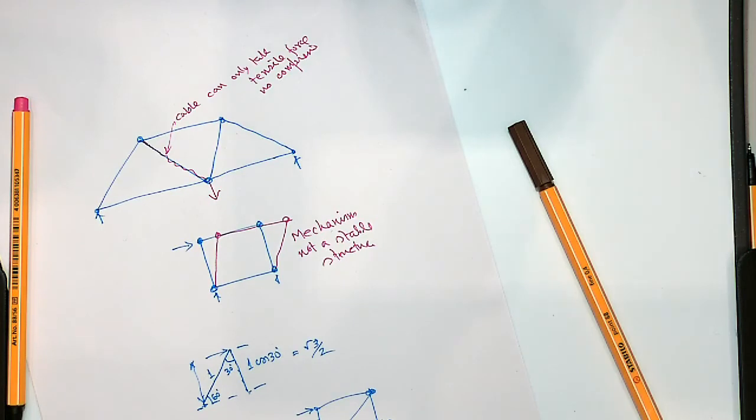Yeah, I just had a question about this question. When I was doing it, because they wanted to find the member, I decided to take my cut around here. Yeah, if you do any other way, then you'll have more unknowns and you will not be able to solve. So if you take the cut here and you just have this unknown and these forces, then you are able to solve. Not wrong, but you'll not get the solution.